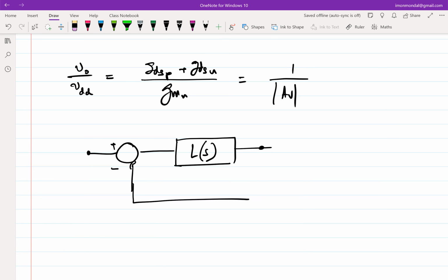And we close the loop here. If you remember, we modeled some injections. This injection can be anywhere in the loop. We modeled it here. And I asked you to figure out what will be the effect of, let's say, Vn on V out if the loop gain is very high, or whatever will be the loop gain, right? And what did you find? It used to reduce by the factor of the loop gain, right?